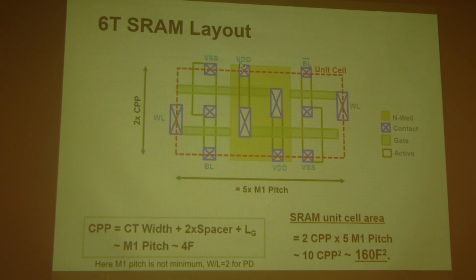Firstly, you want to find this yellow box here. If it says n-well, even if I don't show this label for you, you still need to figure it out. If this yellow part says n-well, you know this is the PMOS region. PMOS is built on top of the n-well. The substrate of a PMOS transistor is N-type substrate. So that means this is the PMOS region, okay?